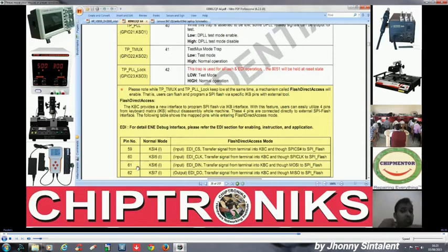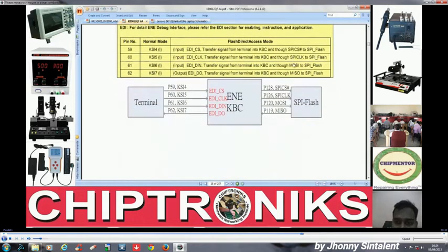You got my concept? I will show it in a video also when I discuss BIOS programming, how to flash this embedded flash inside the 9012 via the TL866A. You don't require any new kind of BIOS programmers. Some people are selling stuff for programming this embedded flash, but in fact you do not require it if you understand this data sheet. So this is flash direct access, and this is only in the 9012.